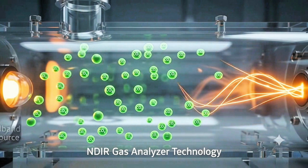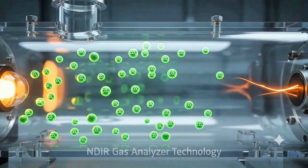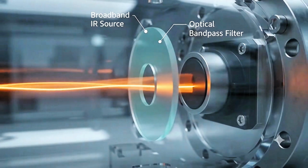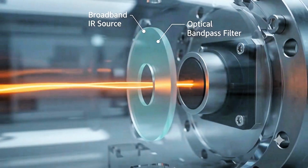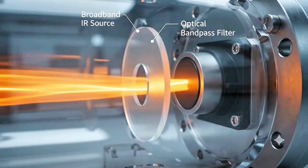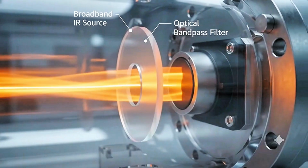To sum up, NDIR works because every gas has its own infrared fingerprint. A chopped infrared beam passes through the sample, a filter isolates the wavelength we care about, and the analyzer compares that against a clean reference to calculate concentration. Keep the sample dry, keep the optics clean, and keep your calibration current, and this analyzer will give you reliable numbers shift after shift.